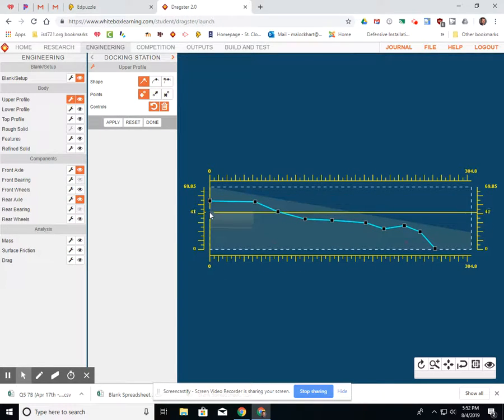One of the other things you need to understand is you have to maintain a 4mm distance from any point on this CO2 cartridge hole to any part of your line. So if I set my yellow crosshair right on the top of that CO2 cartridge hole, it says I'm at 44mm. That means my closest line can be is 48 to this. So I look up here and I got that line at 53. I'm good with that. I could even move that closer if I want to.